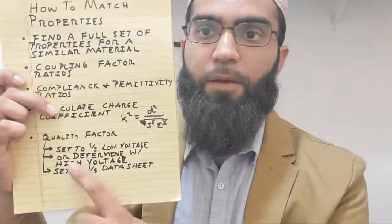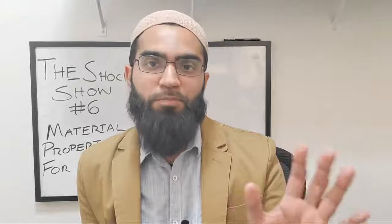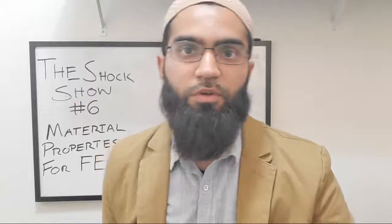So what I suggest for the quality factor is, firstly, the best thing is to start not with the data sheet, but with something you've measured in the lab, because manufacturers' data sheets always tend toward telling you the high side of quality factor. They don't tell you the low side of what you're actually going to end up measuring in the lab from their materials. That's what I found practically. They say the quality factor is 2,000, you end up measuring 1,500, something like that always ends up happening.